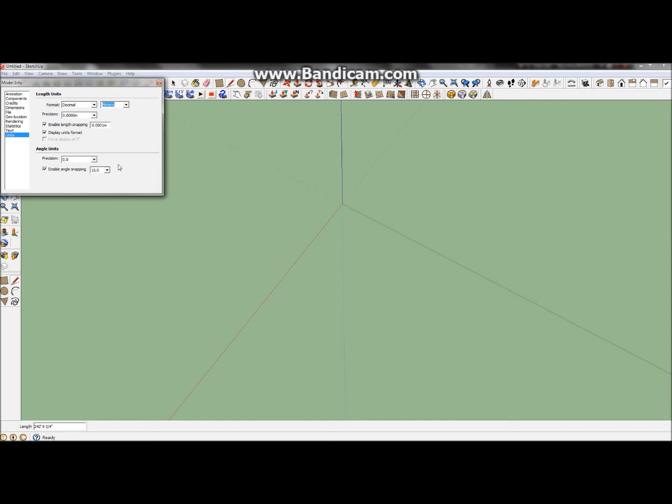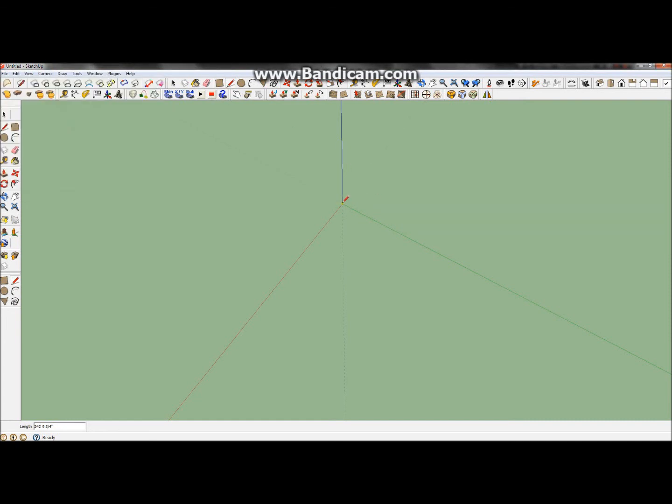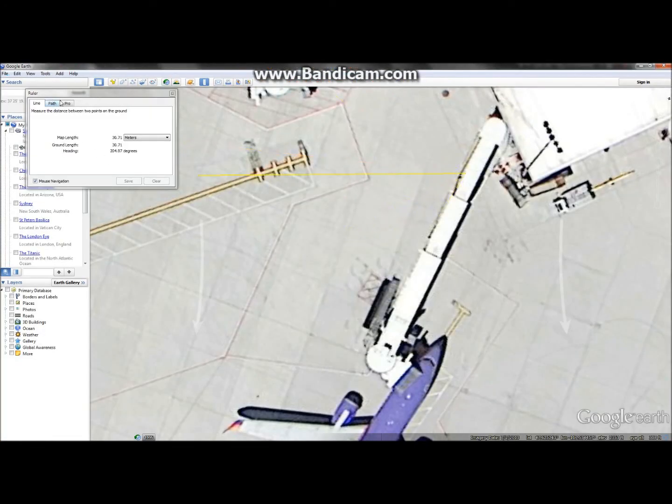That'll probably work. Angle edge snapping, let's set it to 10 while we're here. All right, see how that works for us. All right, so let's do this to 1.8. And let's go ahead and take the lengths of these real quick. Probably take the length of one. Assume they're all about the same.